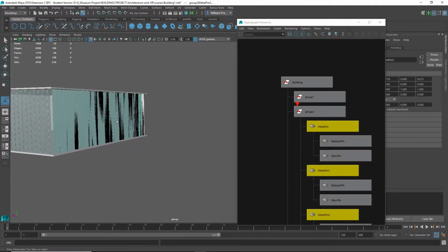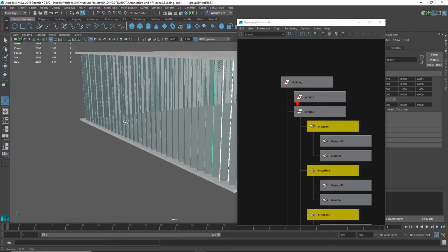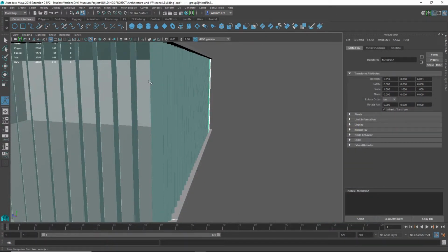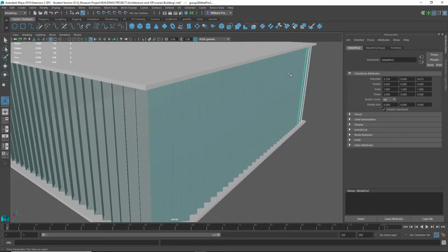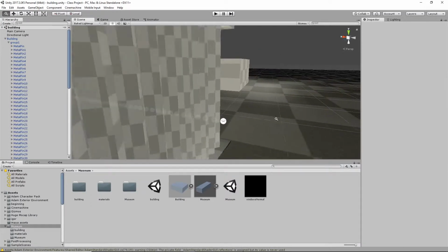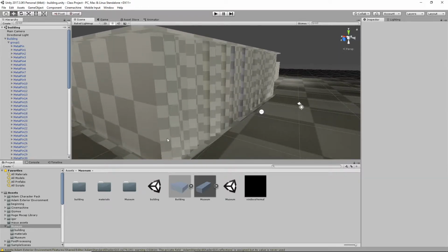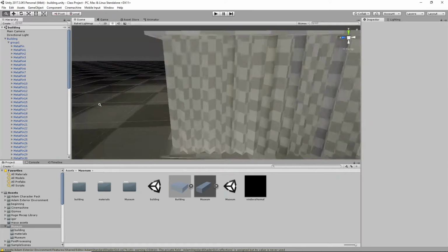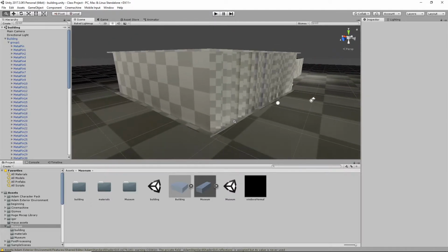So yeah, I had to go and fix these UV maps because I was rendering way too many texels on these little flat planes, and that's what was eating up the render time. It still took a while after I'd fixed that, but once I had, it was a little bit more reasonable. So now when you see that model back in the engine, all of these are mapped out square. And if you look at the sides, they're just little parts of squares, which is what we want, because we don't want that many texels on stuff that doesn't really matter.